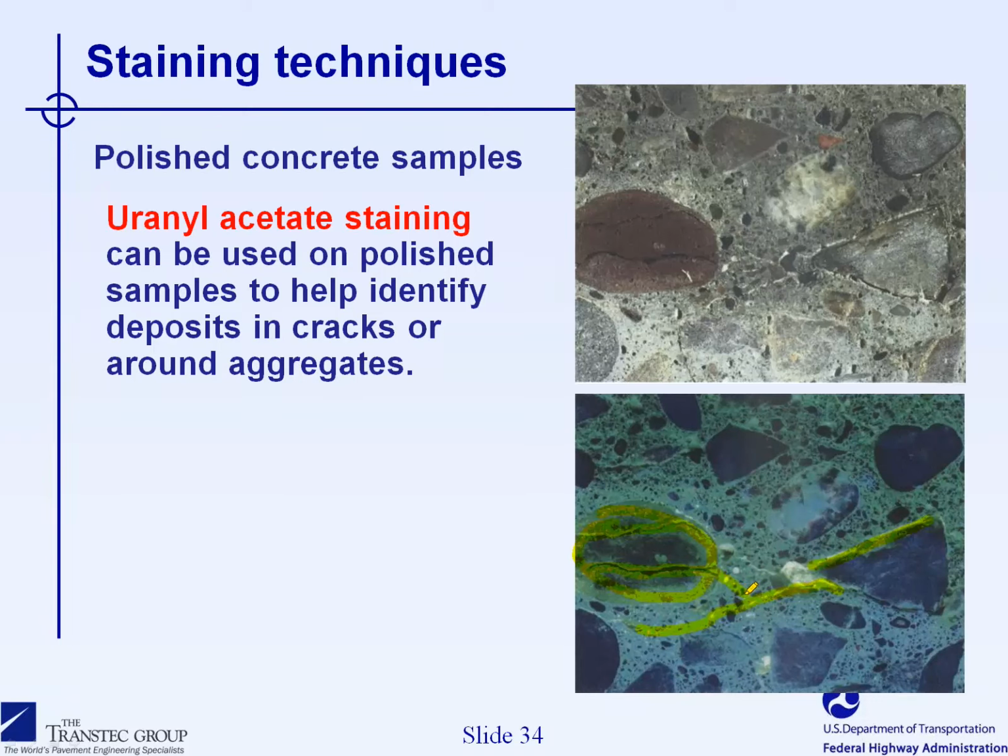The voids that we see being filled by products, like for instance in this slide here, are those that are met by cracks, where the gel running through the cracks will be dumped into the air void at this stage.